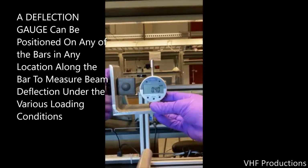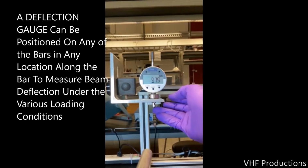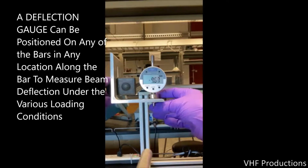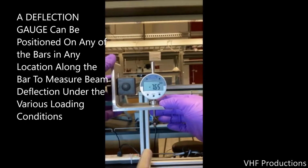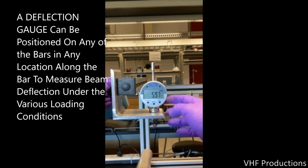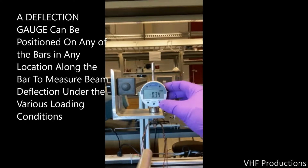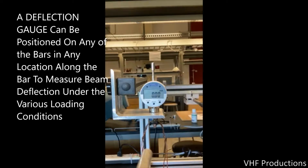In order to get accurate measurements of the deflections, what we're going to do is set up a basket to hang from the beam at each of the 4 length positions L1 through L4. For each case, we're going to load the beam with 1 kilogram of load. So before applying the load, we need to attach the basket and then zero the displacement of the beam under that condition of just the weight of the basket being applied. We also zero the strain gauge output at the same time.